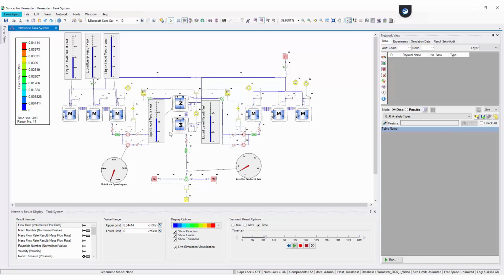As the simulation progresses, we can see the level in the 2 receiver tanks dropping. When they reach a pre-configured set point, the pump starts, and we can see the level in the outer storage tanks dropping while the receiver tanks fill. And through this, the supply to the consumers is maintained. Once the receiver is topped up, the pump will be switched off again.